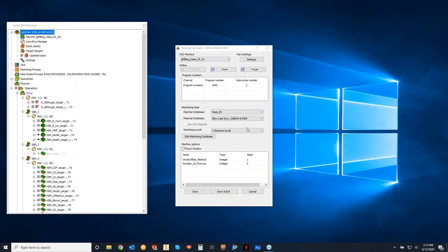And with our machining, the change of feeds and speeds is more related to the machine and the material. So rather than putting this on my Haas machine, machining, in this case, cast iron, maybe that week we had to make this out of aluminum and we had to put it on the other machine. Maybe that's the Mazak on the other side of the shop. You come in here, you change your definitions, resynchronize, recalculate, and now you can actually even save it as a different file.